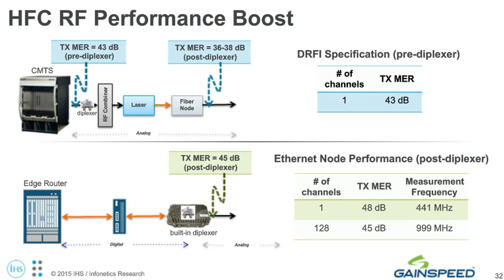But it also gives us the ability to provide a much better RF signal onto the coax, and therefore a much better quality of experience to your end customers. Because we do that direct digital synthesis in the node, everything is digital until we get to that Ethernet node, and then we get to that first analog link. You see a much improved signal to the home. So when you talk about getting that end-of-line SNR for 4K QAM for DOCSIS 3.1, we see that being a very easy proposition in this architecture, while we see it as impossible in this legacy centralized architecture with analog transport in it, centralized CMTS or CCAP.